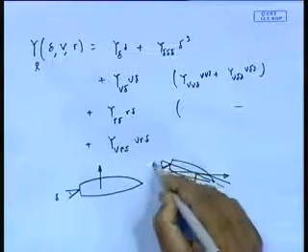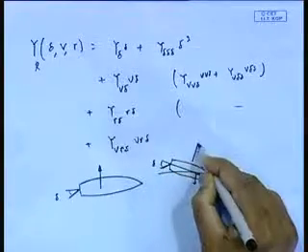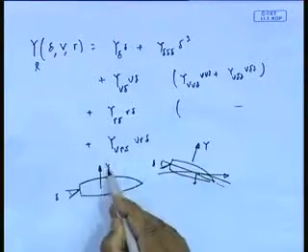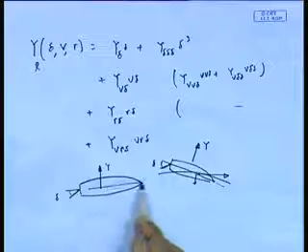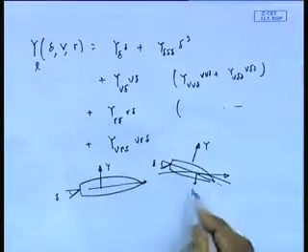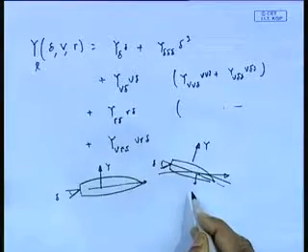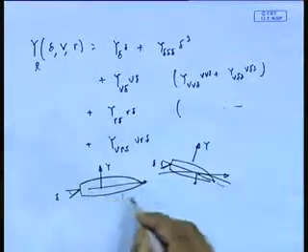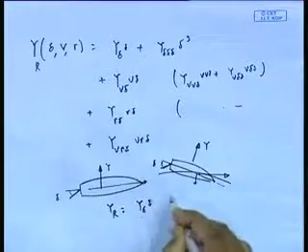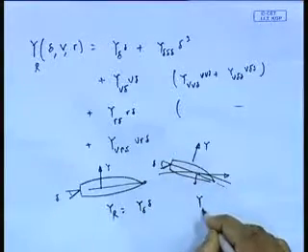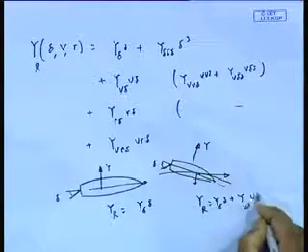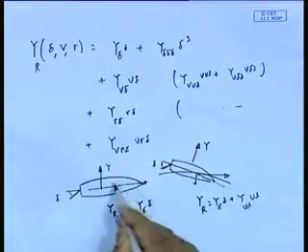So the force that you end up getting here, this y force normal to this body, may not be the same as this y, because in this case the body was going on a straight line, but in this case it is having a small v. So here the force y rudder may be y_delta delta, but here y rudder may be y_delta delta plus y_v_delta v delta. Here, of course, the v is 0.